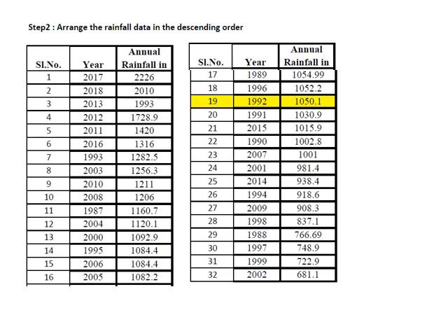My idea is to find out what is known as the dependable rainfall. You cannot design the bund for the highest rainfall, which is 2226 millimeters, nor can you design the bund for the lowest rainfall. So somewhere a via media between the highest and the lowest rainfall has to be taken. For that, we use what is known as the dependable rainfall. Dependability is generally taken around 60 to 75%. Taking the lower side, we take dependable rainfall as 60%, of the total number of years of data collected.